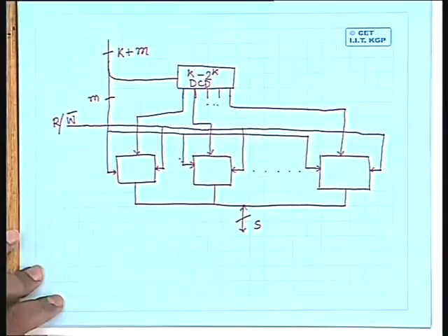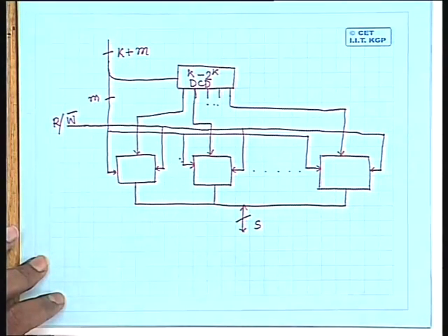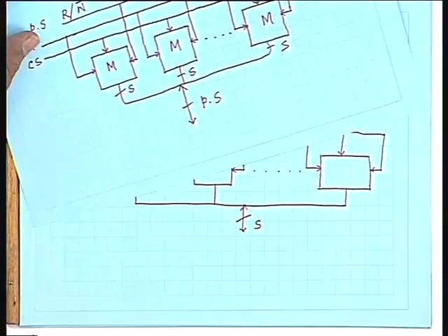And this connection is possible because we said when we discussed about the memory cell that for every input and output, for every cell we have buffers. And it is because of the buffers we can connect them together. If there was no buffer, such a connection would not have been possible. Okay. In such a case, what we would have to go for is again a multiplexer, demultiplexer pair. Okay. So this kind of arrangement, whether this one or this one, they are linear arrangements.